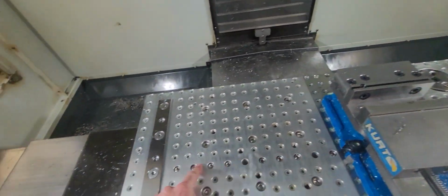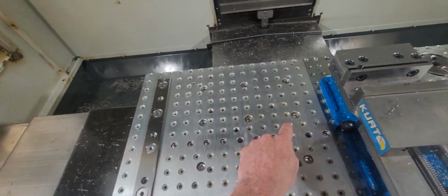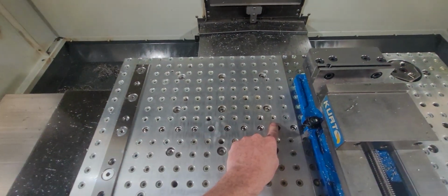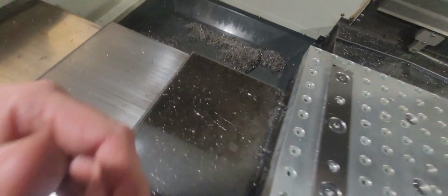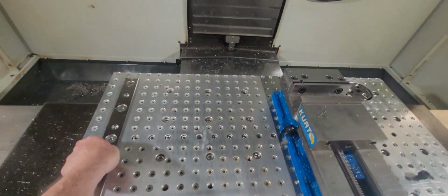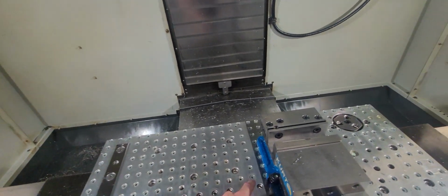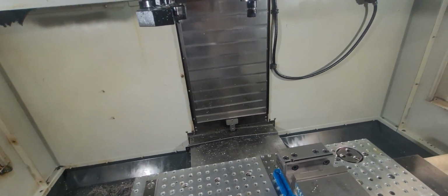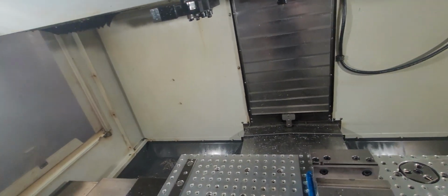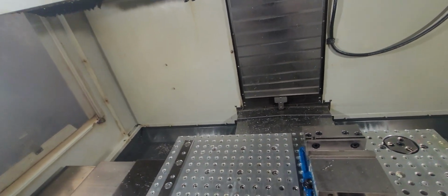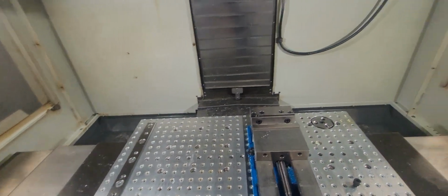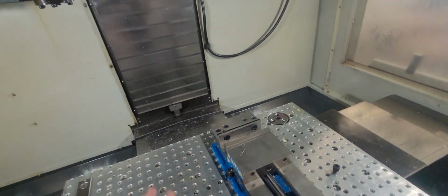Then these holes here, you can see I've got these stainless pins in right now to keep them covered. Down here, inside there, I don't know if you're going to be able to see that too well, but I've got a massive T-nut that runs all the way along here, and there's a pin under here that locates it, so this is always lined up. Then if I need a second vise, no problem, just put that vise on there wherever I want it and go again. Granted, it's on aluminum, not as rigid, but to be honest, most of my work is done on the one vise, but it is brilliant.